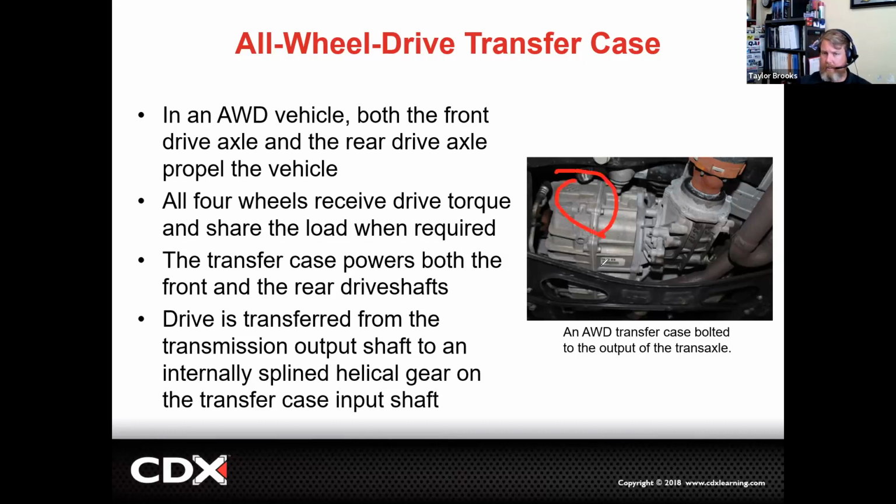So this is going to be our transaxle right here with our transfer case right here. What we're doing is interrupting the right side axle to send torque through our transfer case and then out through the drive shaft, while also going out to the right side, while the left side, or the driver's side, will go straight through. We're usually sending a split of torque, so it's not going to be 100% torque to all four wheels.